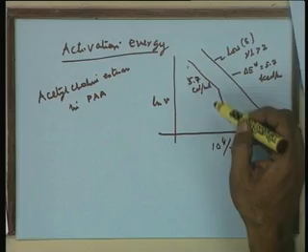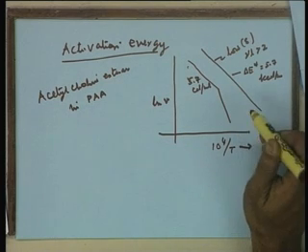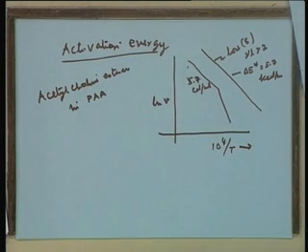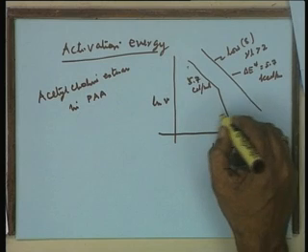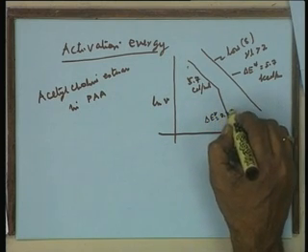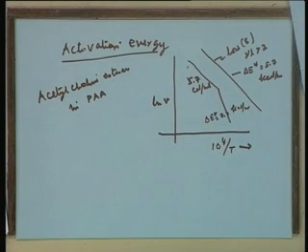On the other hand, when the temperature was reduced, the system became diffusion unlimited, and a much higher activation energy was obtained, about 9.4 kilocalories per mole. So a change in the activation energy over a range of temperature also indicates diffusional limitation behavior.